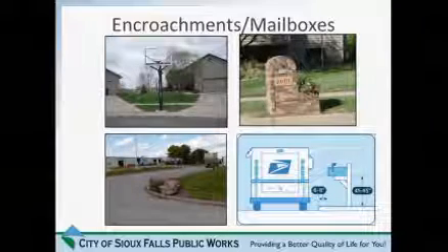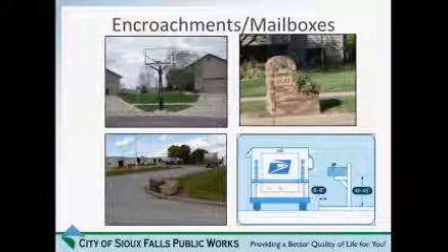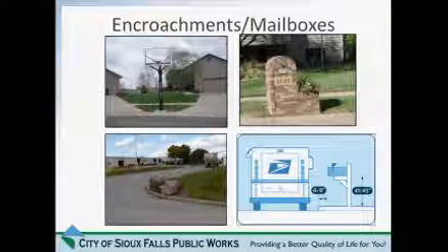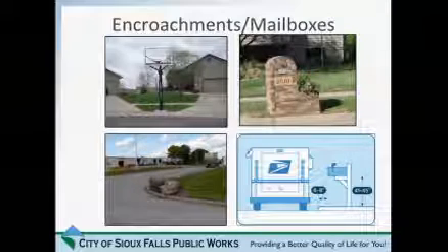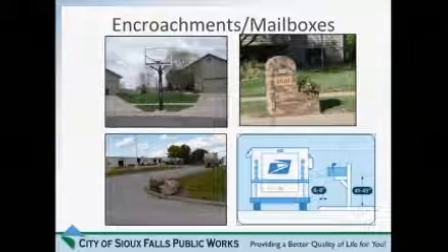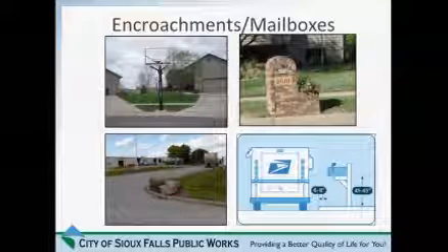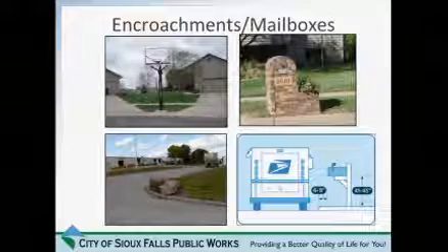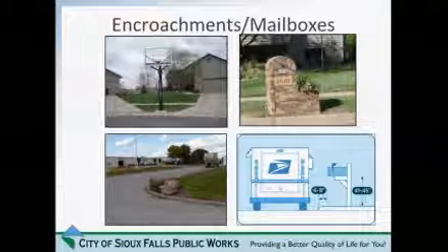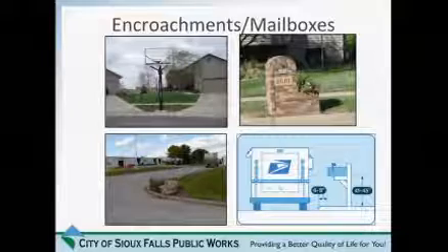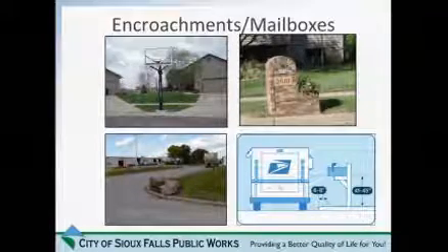It's one of the challenges that we have for several reasons. Do these create a hazard in a right-of-way? You have a large immobile object right back of the curb. Typically most of the objects in our right-of-way, like our signs, our traffic signals, our light poles, all have breakaway bases. So if a car hits them, they shear off, per se. With these mailboxes, if a car hits them, could we endanger the public?